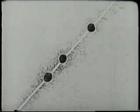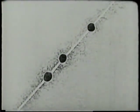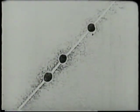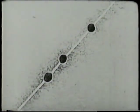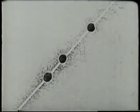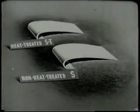In these locations, the particles serve as keys or props which secure blocks of unit cells in position and interfere with slippage. This is the most generally accepted explanation of the increase in the metal's hardness and strength as a result of heat treatment.